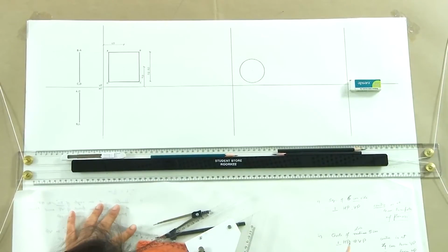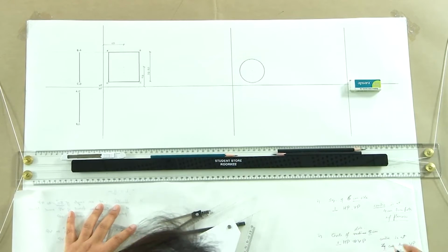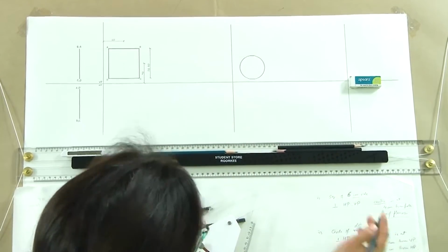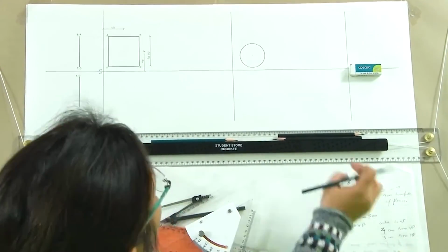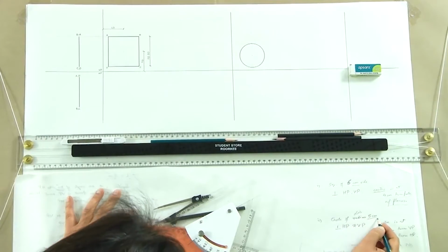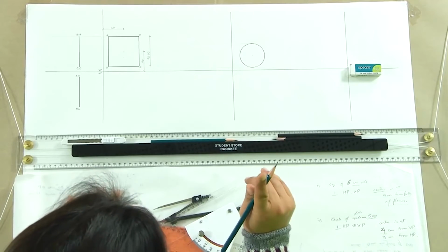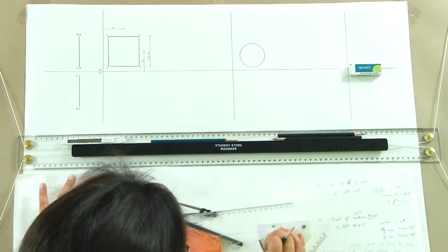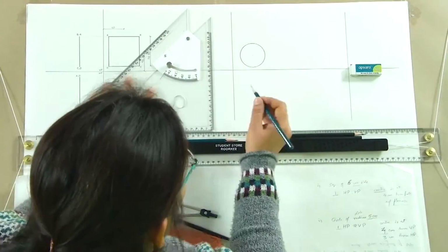Follow how the process that I am taking for drawing this, you will see that any dimension which is given here, I will be measuring only once on the sheet. So, I measured this 4 centimeter only once, I measured this 3 centimeter only once, and I have measured this diameter of 5 centimeter, which is radius of 2.5 centimeter only once. Once I have this dimension here, all other dimensions will be referred or will be derived from the same drawing, which is how geometric construction should always work, right.